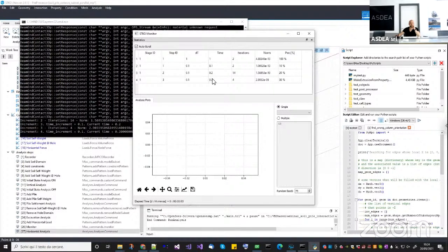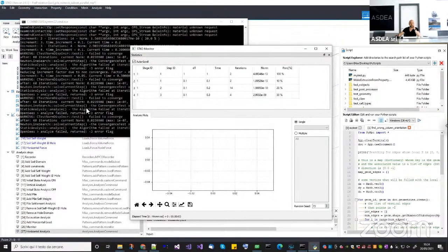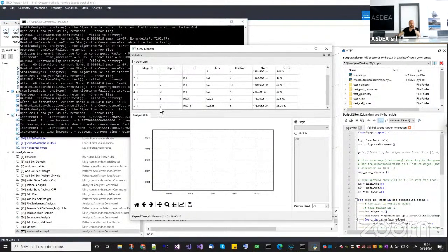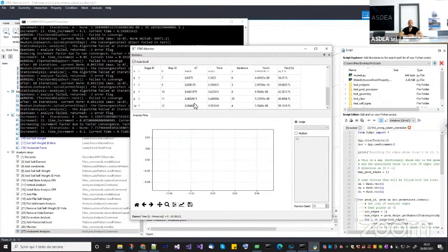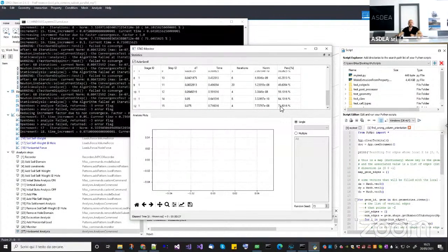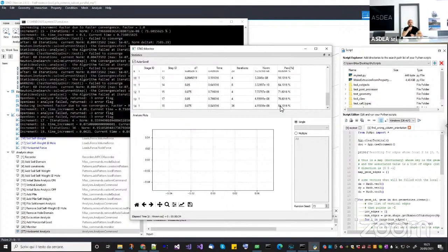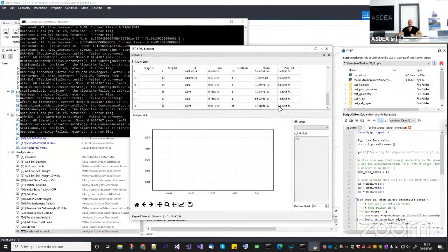Okay, so wait for a second. Okay, now it is going. Yeah, there is some convergence error. So probably it is giving some problem, but it tried to adapt the time step. So probably it will manage. Let's see. As you will see, actually, the contact analyses are very sensitive. So you do small changes and it's going to be a mess. So it is actually now struggling in the vertical analysis because probably keeping the whole domain is giving some problem for the contact, but fortunately it's managing.